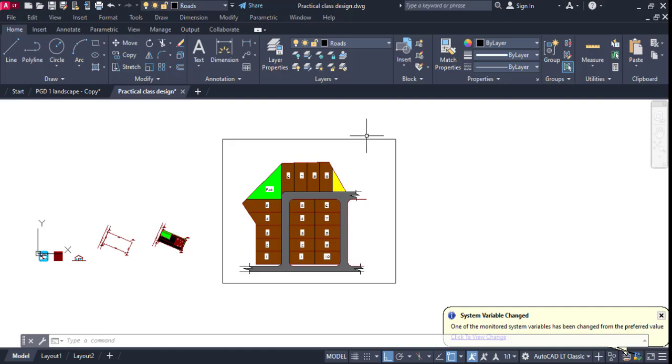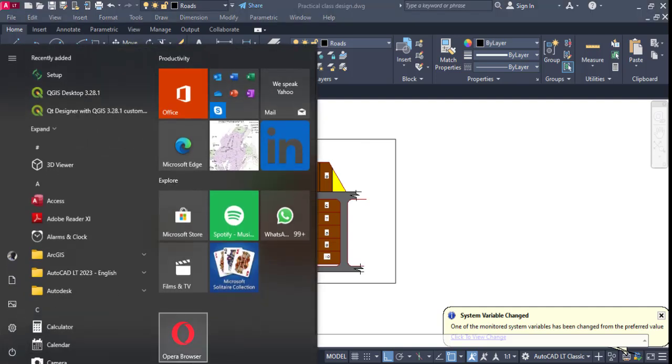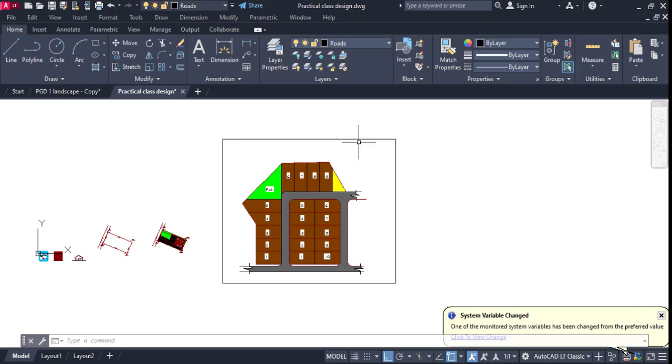However, most of the time, the issues we're having are with scaling. On that note, I'm going to show you guys how to do proper scaling. Now, when you want to scale in your AutoCAD, you have what we call your model space and your layout space. Your model space is where you carry out any form of design you want to carry out. But your layout space is where you ought to print your job. Anything that has to do with printing, you print from your layout space.